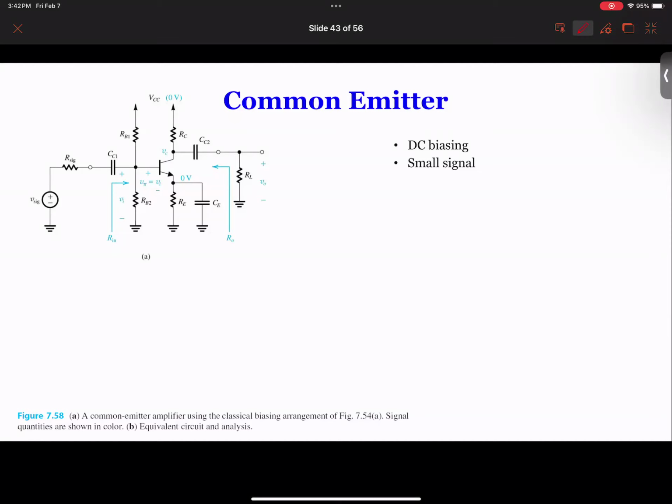This previously was an example to actually do the stuff. So if we want to do a BJT, you see the circuit is almost identical, except the MOSFET is replaced by BJT. So simply, you can do the same DC biasing by eliminating the capacitors, I mean, have them open. You get the DC biasing circuit, and then we plot the small signal circuit after that, right?